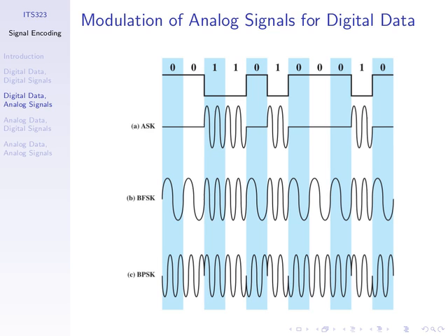And the other two, frequency shift keying, phase shift keying. The B refers to binary in that we have two levels. Change the frequency. Bit 0, some low frequency, maybe a frequency of 1. Bit 1, a higher frequency, say a frequency of 2.